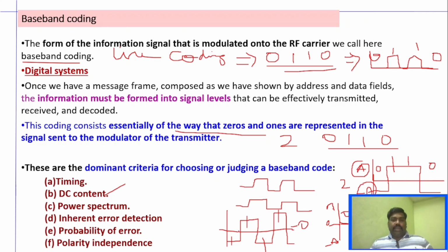There is no distortion. And say for example, there are other line coding techniques where you will have like this, right? For 0 there will not be any values, and for 1 you will have like this. If you take this as an example, right now you have an average DC value, because there are no negative values here, so the positive voltage will not cancel each other, right? So now what happens? You have a DC component, and coding in this particular format is prone to errors. We will have errors. A lot of distortions are possible, right? This is known as DC component.